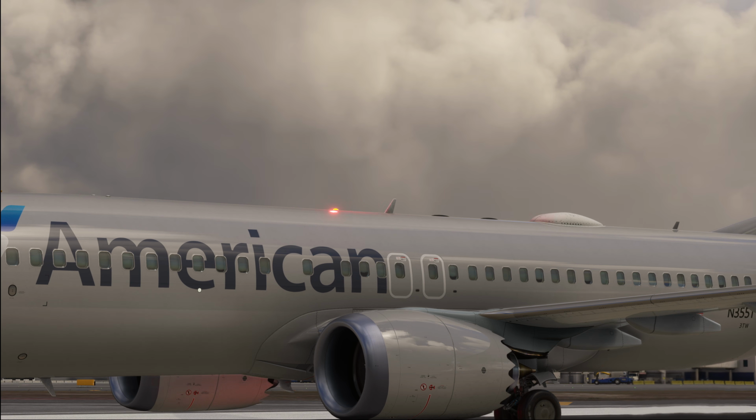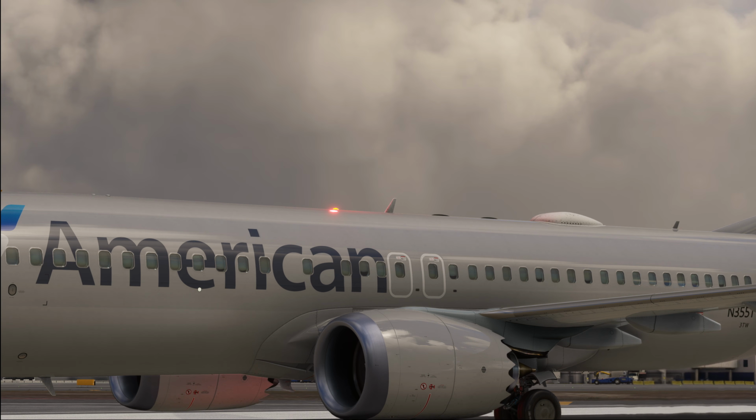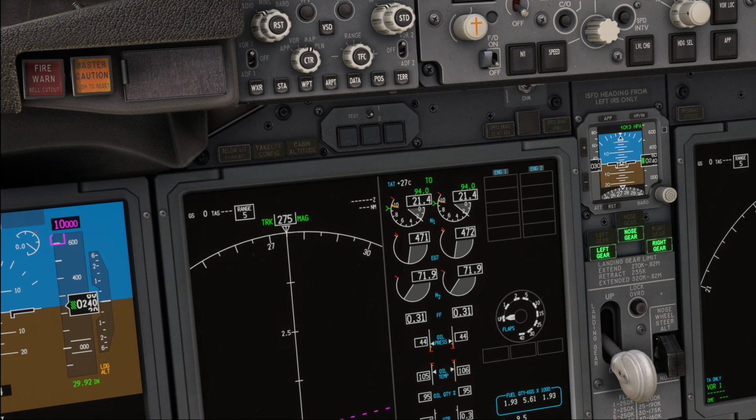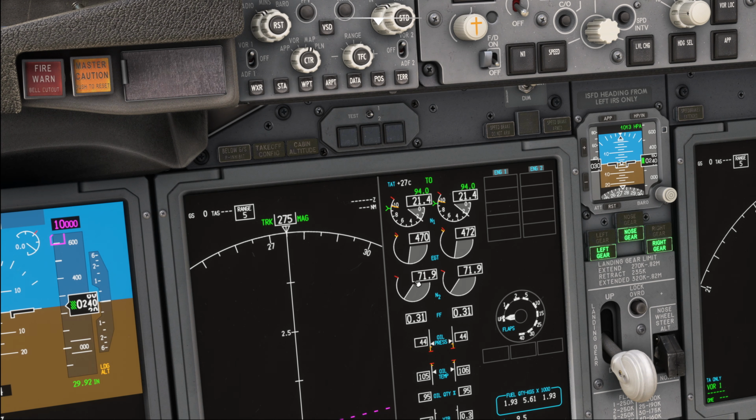Now the BRM timing is variable depending on several factors, such as the time since the engine shutdown, internal engine temperature, ambient temperature, etc. BRM will be active for approximately between 6 and 90 seconds and is only active for engine starts on the ground. When BRM is active, a motoring indication will be shown on the N2 display during the engine start on the ground.